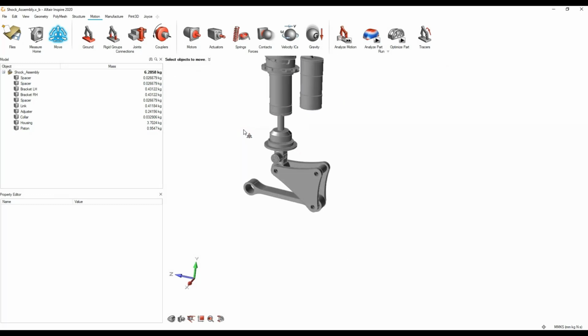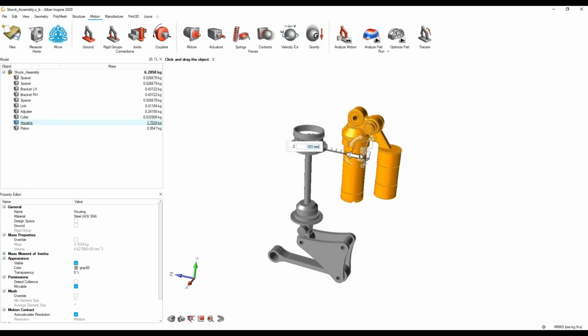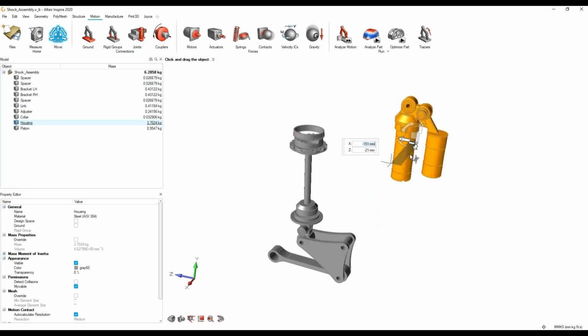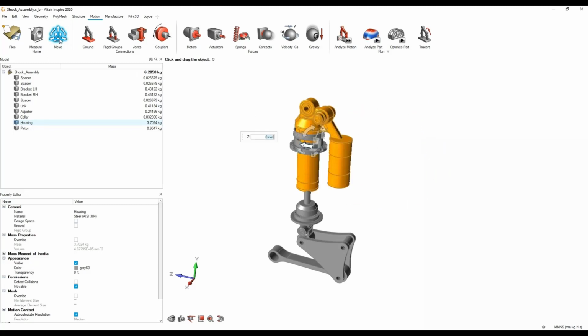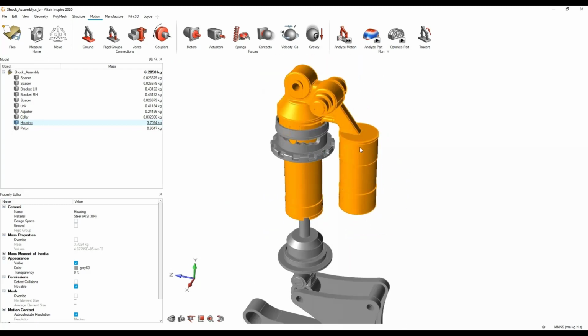The move tool, you can easily specify exactly what it is you're moving. If you were to click on a part, you can easily manipulate it in the Z axis or on a plane itself, where you can easily just drag and drop it. So feel free to use the manipulator tool. If you do need to look at translating your parts around and moving all around, then you can easily interact with it using this tool here.